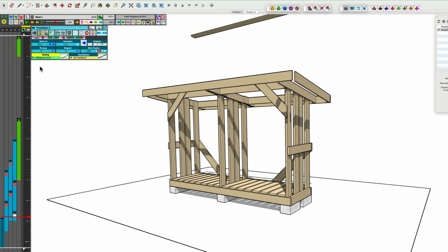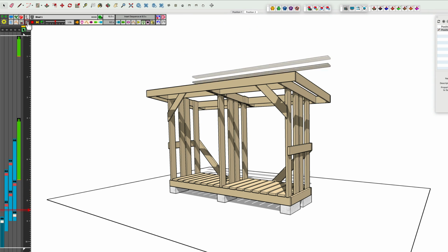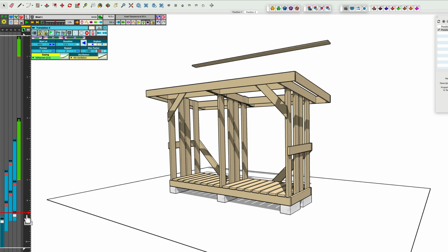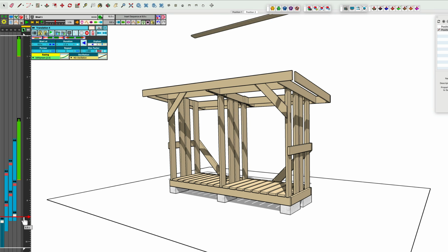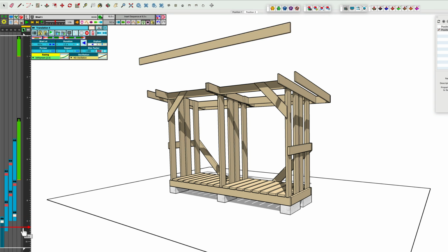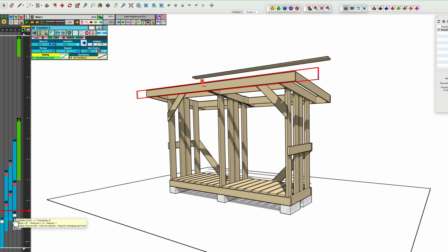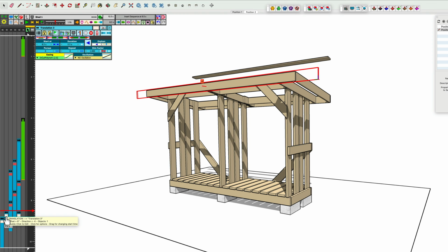So the effect when I play the animation is it looks like the board curves away from the shed before it goes skyward. This is what an overlap of these 2 moves creates. For a quarter second or so, the board is moving both toward the viewer as well as upwards. So I can then copy that first move in the X direction and apply it to the fascia board on the back of the shed, and change the direction to -6 inches.